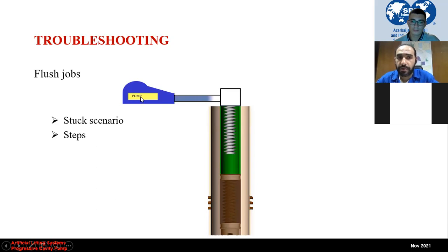As we said, we'll pull the rotor out, start to pump, then fill the tubing till the fluid reaches the stator. Normally, the flush fluid volume will be around 1.5 times the tubing capacity. And remember that you have a rubber element inside the well. You cannot flush with diesel, you cannot flush with chemicals. Take your precautions to avoid damaging your stator elastomer.